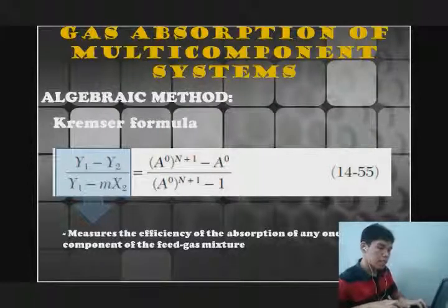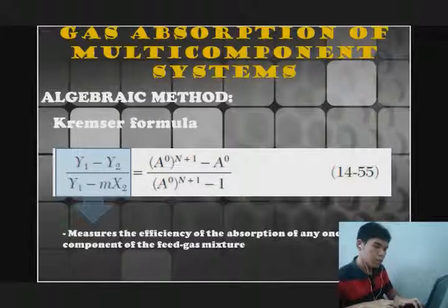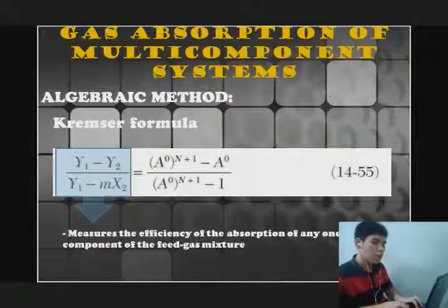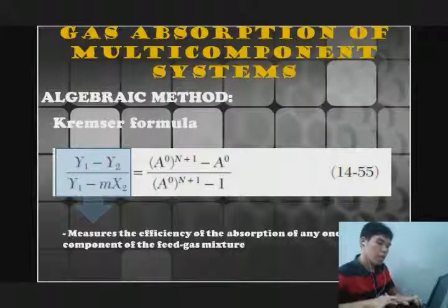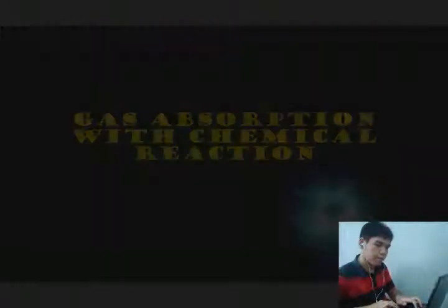When the number of theoretical plates n and the liquid and gas rates have been fixed, the fractional absorption of each component may be computed directly, and the operating lines need not be placed by trial and error, as in the graphical approach described earlier.